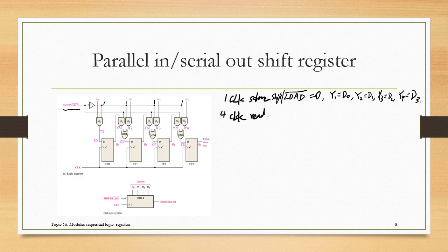Also, since this line is 1, the other line is 0. So one input for G5, 6, 7 is 0, which means the outputs Y5, Y6, Y7 are equal to 0. For the OR gates 1, 2, 3, one input is 0.